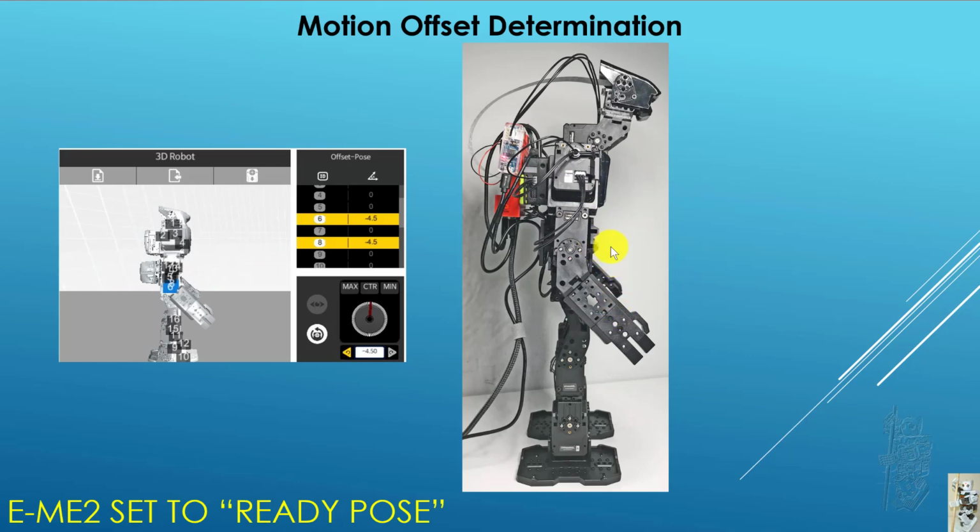But I noticed that sometimes when it goes backward, not all the time, but sometimes, this robot will fall on its face. Meaning that somehow the CG starts getting too far forward beyond its toes here, so it would fall. And the funny thing is, I tried different numbers, minus 4, minus 4.3, maybe going to 5, and so on. And I couldn't find one that worked for forward and backward at the same time. One of them would fail, but the other one would be good.